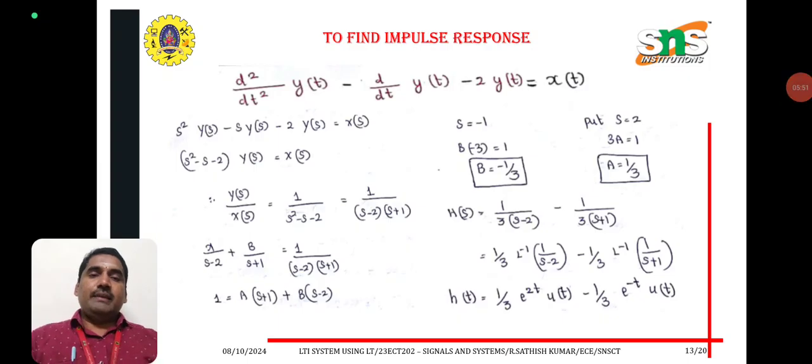Next one, to find the impulse response of the system, d²y(t)/dt² - dy(t)/dt - 2y(t) = x(t). Applying the Laplace transform of the above function, s² Y(s) - s Y(s) - 2 Y(s) = X(s). Therefore, Y(s)/X(s) = 1/(s² - s - 2) = 1/((s-2)(s+1)).